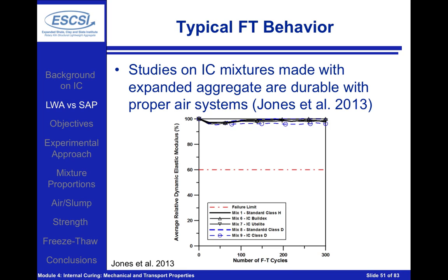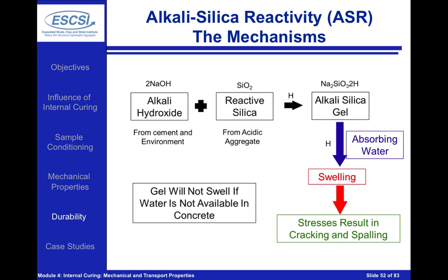The whole idea behind this is that the aggregates themselves are durable, and water is pulled out of the aggregate for internal curing. What we're going to notice is that a properly air entrained concrete is going to behave very well in freeze-thaw.